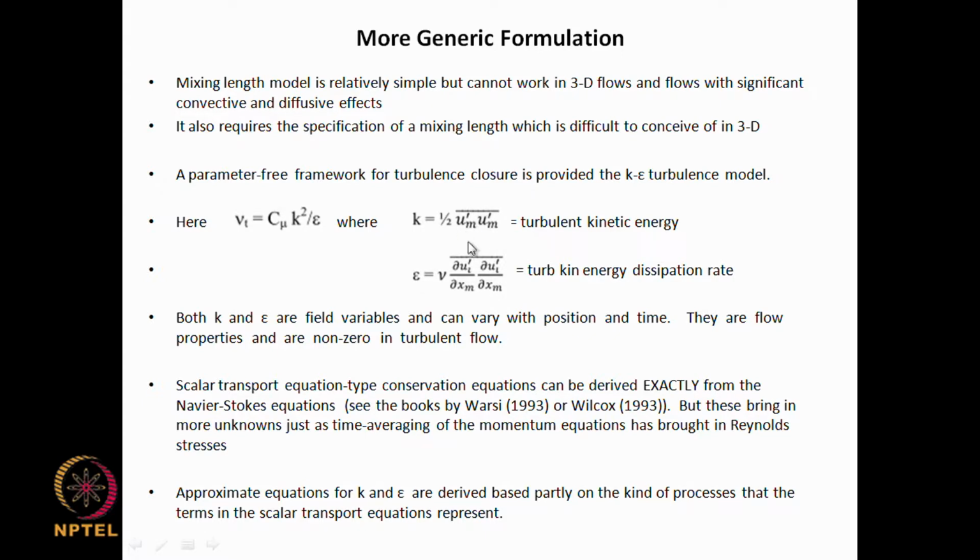So, this is always positive, or 0; it is 0 only in non-turbulent flow. Whereas here this is talking about velocities and here it is talking about velocity gradients, and this is multiplied by the kinematic viscosity of the fluid, which brings in this idea of energy dissipation, because viscosity has an energy dissipation role there.